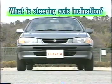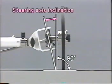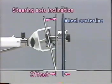Steering axis inclination is the angle between the steering axis and the plumb line as viewed from the front of the car. It is also called the kingpin angle. The distance between the intersection of the steering axis with the ground and the wheel center line with the ground is called the offset or scrub radius.